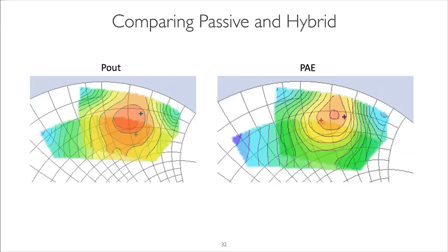In this case, we were able to use a smaller amplifier. If we had done this purely actively, it would have taken a much, much bigger amplifier to match this, because the mismatch loss is very high. We were looking at the mismatch loss going from 50 ohms to 2-3 ohms. Well, this is almost an example of this. You're going from 50 ohms, or let's say 0 gamma, to probably 0.85, almost 0.9 gamma. To overcome that mismatch with an amplifier is doable, but it can become very expensive.